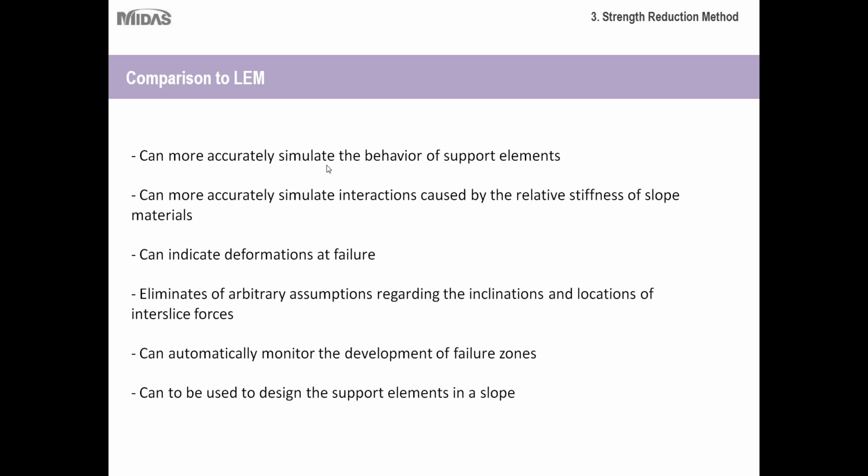that process. So instead of having a separate system to analyze the factor of safety, in other words, a limit equilibrium method, and then another system or work process to do your design, and having to go back and forth between the two, you can just use the strength reduction method to do the factor of safety and your design. So it's very convenient in that respect.